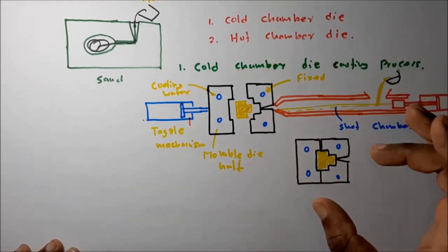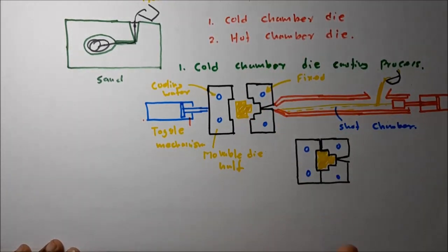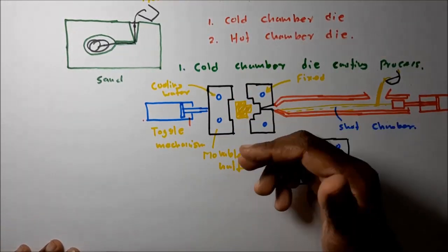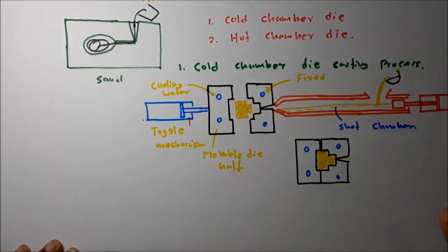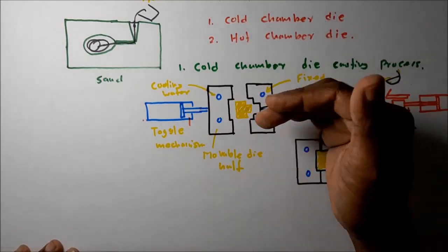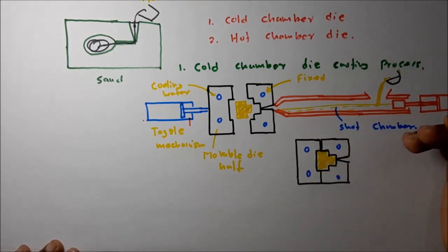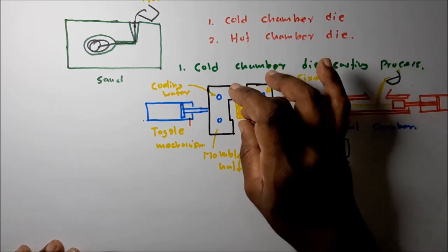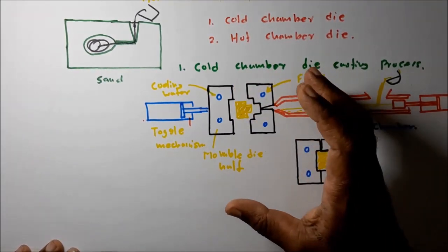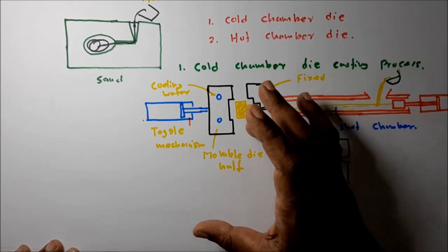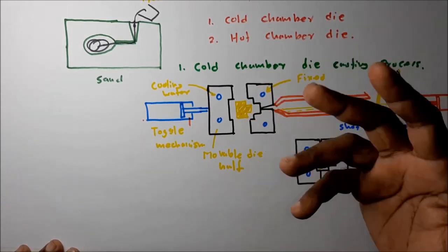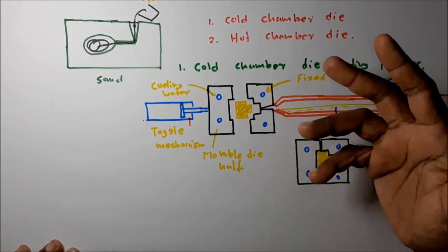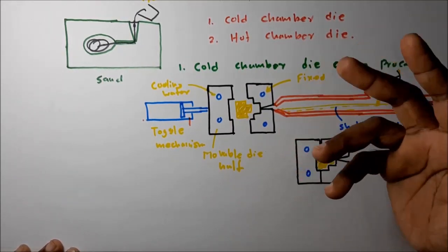This cyclic process actually has a greater production rate, because the solidification time can also be controlled and minimized by applying the water-cooled channels. Then if we use a mold with multiple cavities, the production rate can further increase.